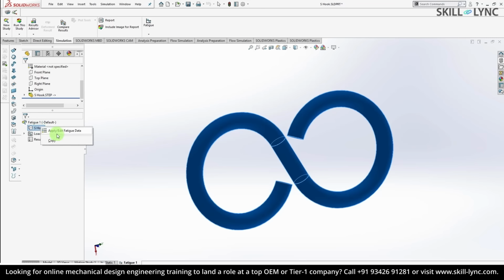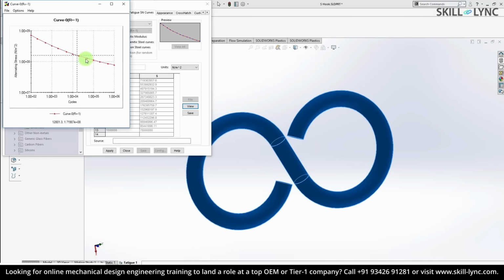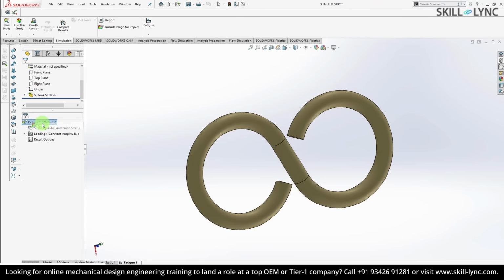Once we do this, we are all set to proceed with the simulation, but we haven't yet defined the SN curve for this simulation. So right click, apply or edit fatigue data. We have an option to derive from the material elastic modulus. Select that, and we have a table that is populated here. Click view to plot data in the SN curve. Here you have the number of cycles. This is the maximum stress that is allowed, and click apply. We are now good to run the simulation.